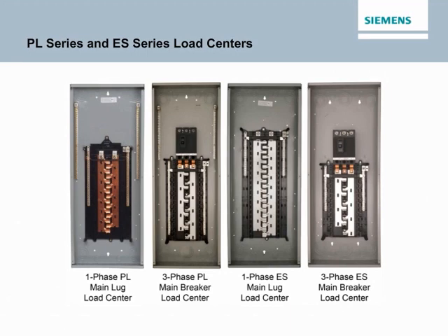The ES series load center offering offers the following features. Invertible for bottom feed applications, Insta-wire neutrals and grounds, aluminum bus bars, single-sided neutral on load centers with 24 circuits or fewer, single-piece carton, and a 10-year warranty.